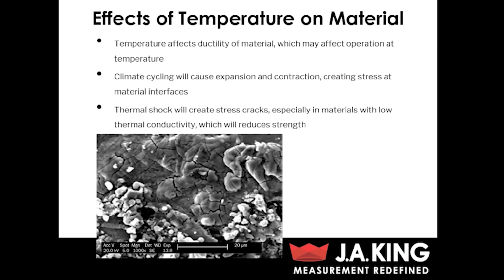And then thermal shock testing involves a rapid change in temperature, and this can create stress cracks on the surface of materials, especially materials with a low thermal conductivity. Oftentimes, you actually can't see these surface cracks with the naked eye, but if you see that image down at the bottom of the screen, that's a magnified image where you can actually see some surface cracks. And over time, those surface cracks will reduce the strength of the material.